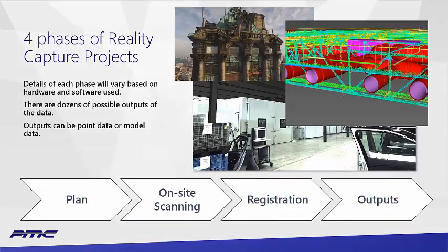Expect the project to unfold in four different phases. Again, this is specifically for scanning. We're going to start with a plan. We're going to go on site and complete the scan. The scan will have to get registered, which we're going to talk about in just a minute, and then outputs have to be generated. So it's important not to confuse the completion of on-site scanning with final data delivery in a usable format. There's still quite a bit of time involved after the on-site work